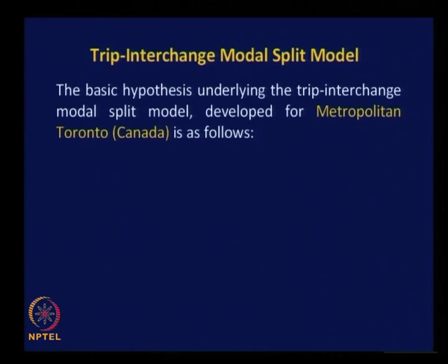So with this understanding, let us proceed further and see one more type of model which was initially developed, named trip interchange modal split model. The basic hypothesis underlying the trip interchange modal split model developed for Toronto metropolitan area in Canada is as follows. There are certain assumptions or hypotheses based on which this trip interchange modal split model was developed. The assumption is this: